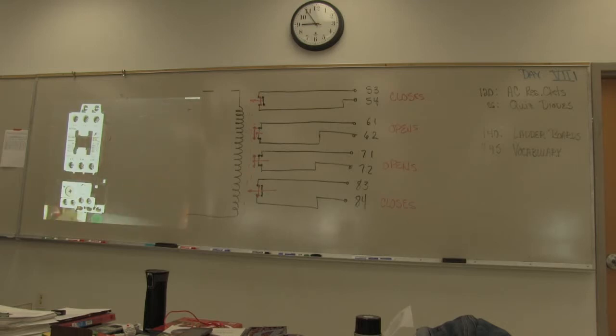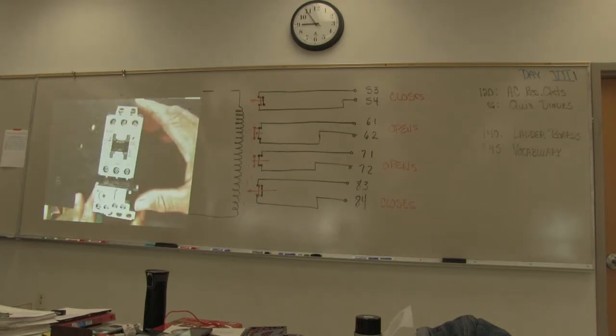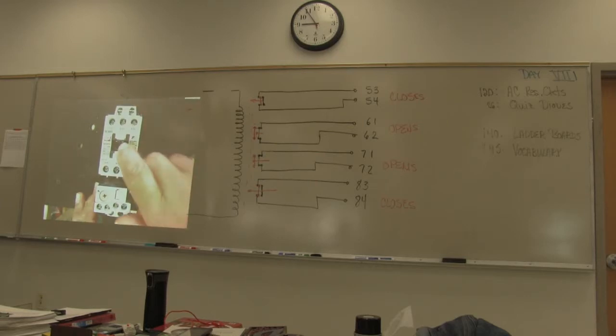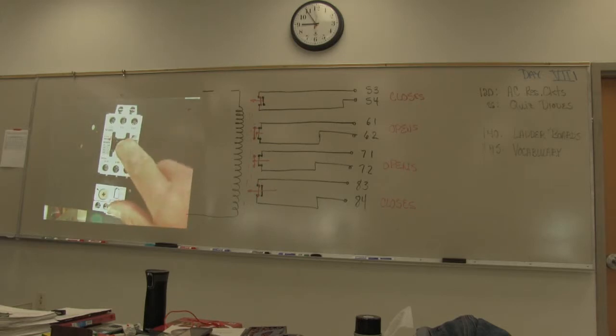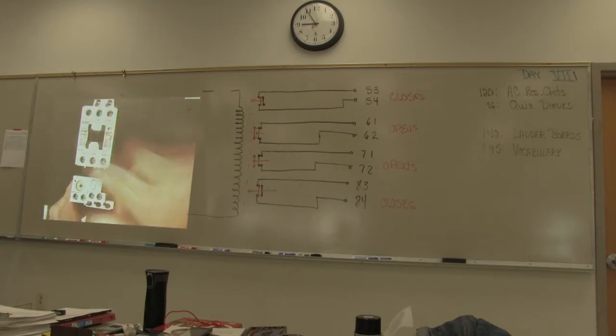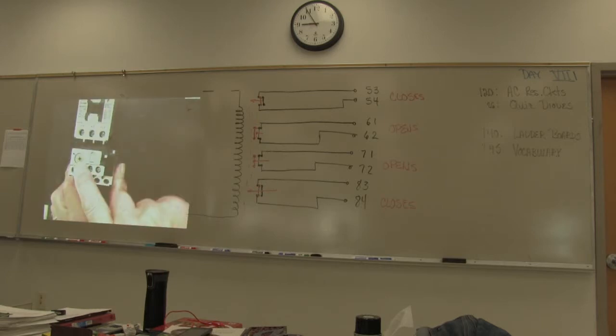This one, however, since it is a motor protection, we only need the normally open version, because there's no reason to ever keep it closed and then open it. This is designed so that when the coil gets energy, the motor turns on, right? 3 phases, 1, 2, 3, L1, L2, and L3. Here is our temperature adjustment. This is our sensitivity adjustment that we can make right here. And there's a reset button. Now, what's the temperature that it's reading?